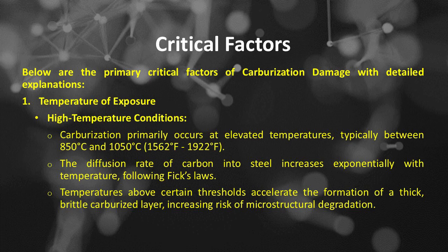Number 1 is temperature of exposure, which includes high temperature conditions. Carburization primarily occurs at elevated temperatures, typically between 850 degrees Celsius and 1050 degrees Celsius, or 1562 degrees Fahrenheit and 1922 degrees Fahrenheit.